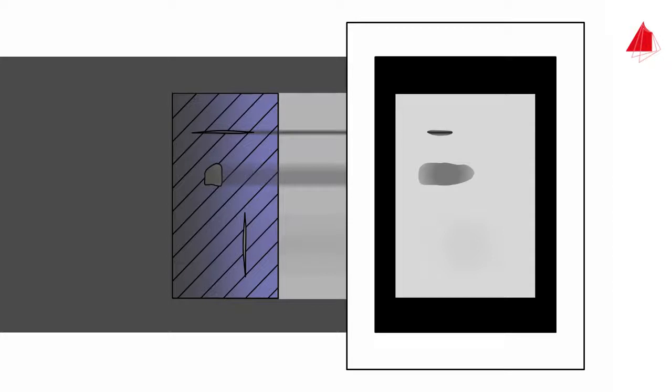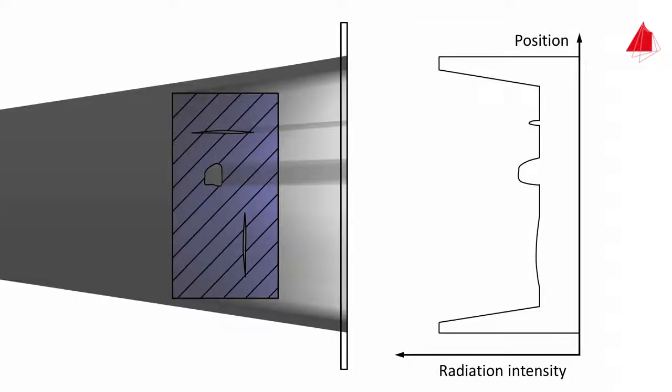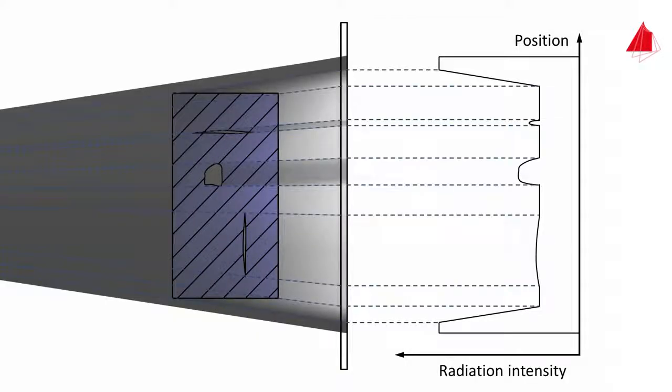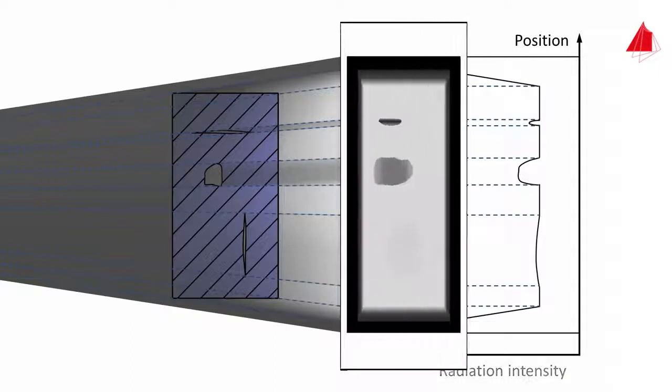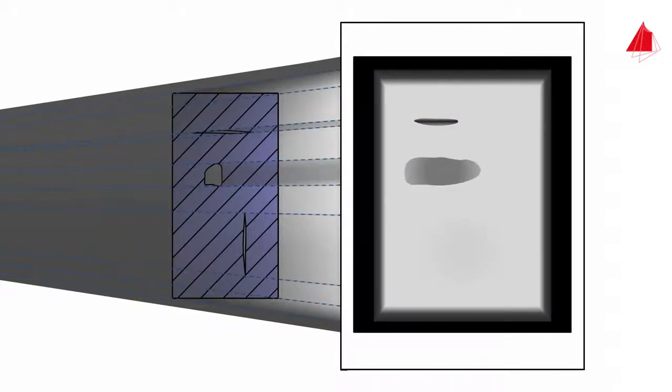This X-ray image is only obtained with parallel radiation. Using a classical X-ray tube, however, the radiation is cone-shaped. The intensity distribution will therefore look different, and as a consequence, also the X-ray image. The edges of the sample now appear three-dimensionally and not as clearly outlined as before.